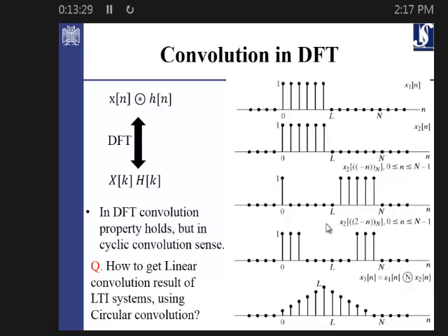So the circular convolution of 2 rectangular windows would be a triangular window. And the size would be increased. In the case of the convolution, we know that the size will be increased. The size is now increased. Yes? This is the same as convolving 2 box signals, right?